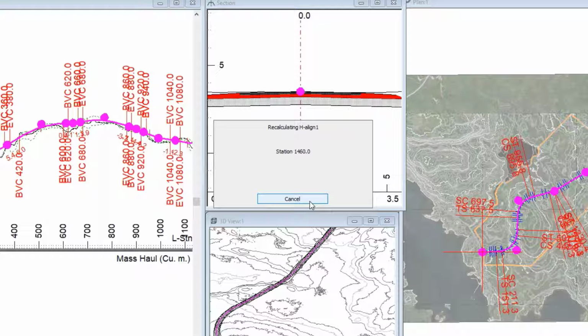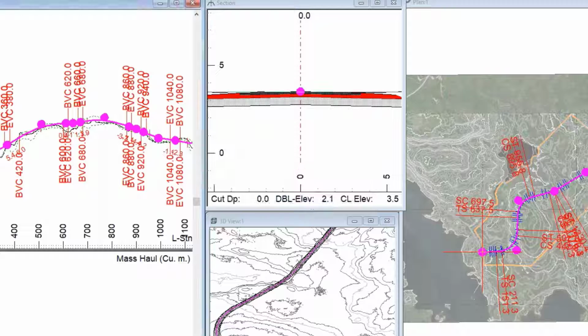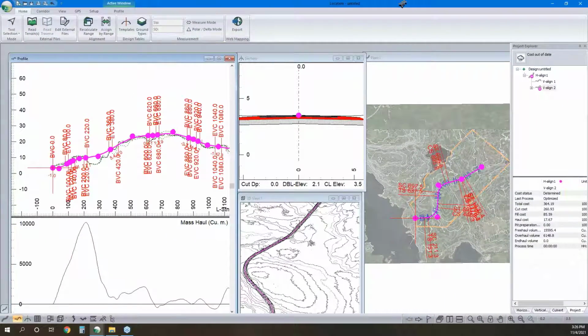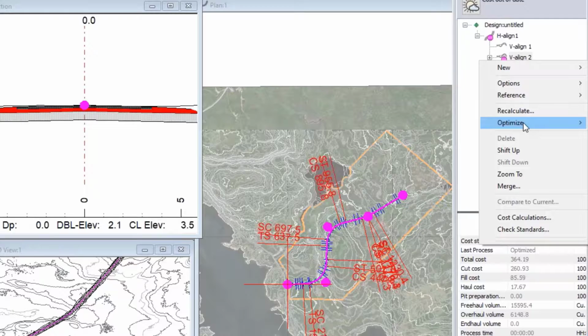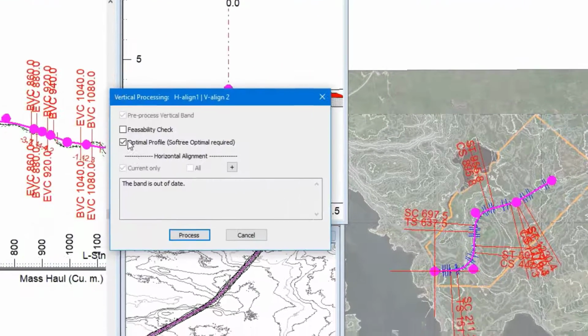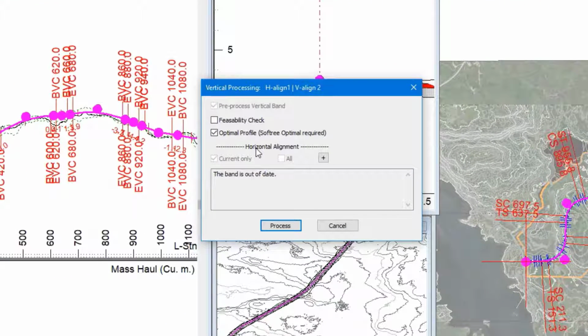But we can eliminate having to come in here, click optimize vertical, and if I just optimize this, it's going to have to run through, do the sampling. So that same sampling that we just waited for. And then it's going to search for the best alignment. And it may take a while before it realizes that there is no best alignment, because no alignment fits.